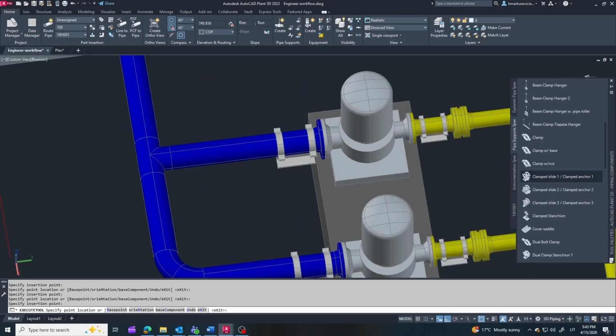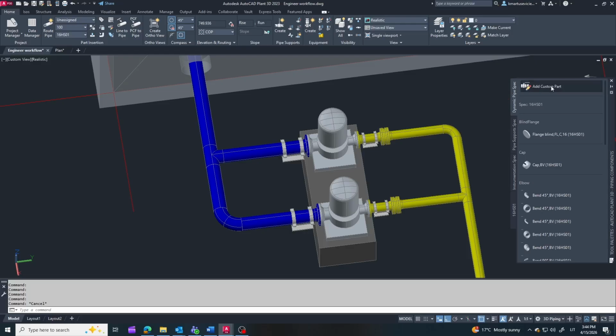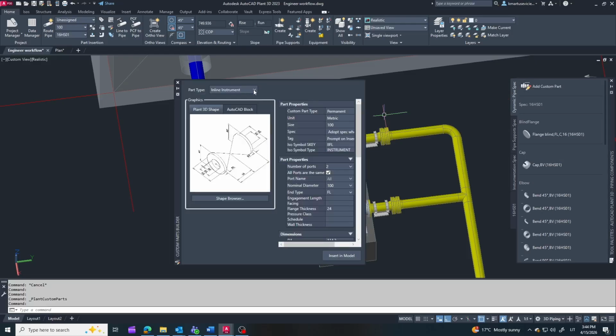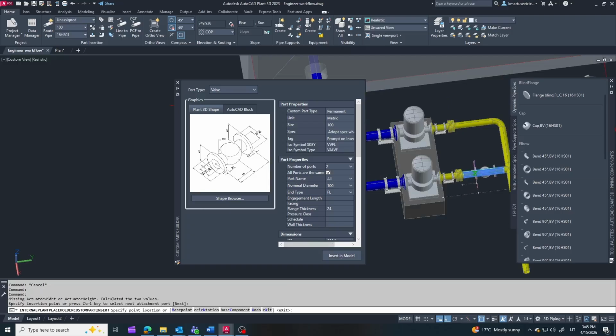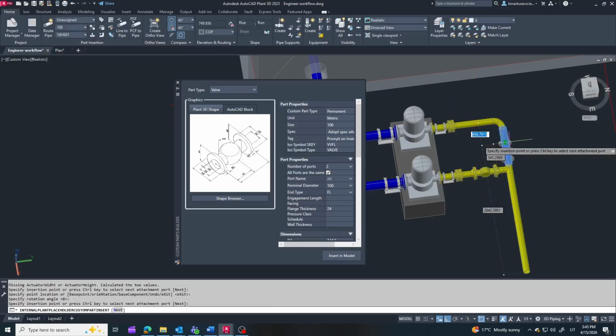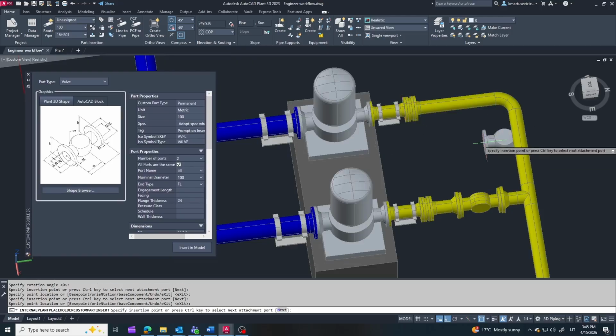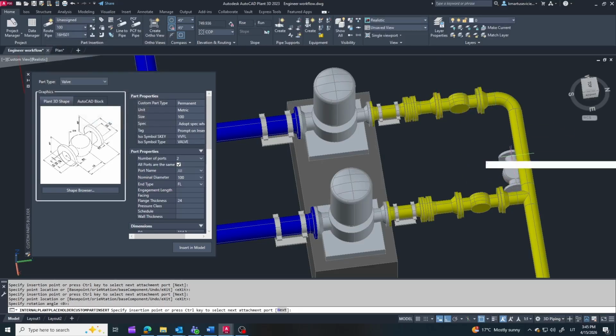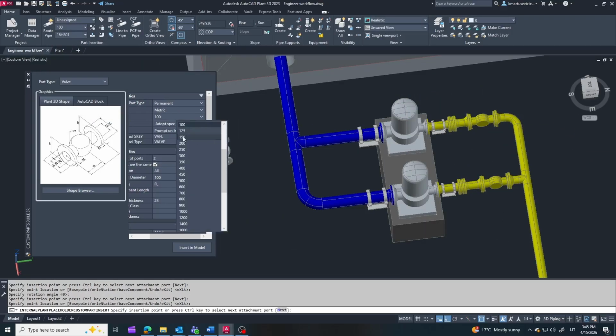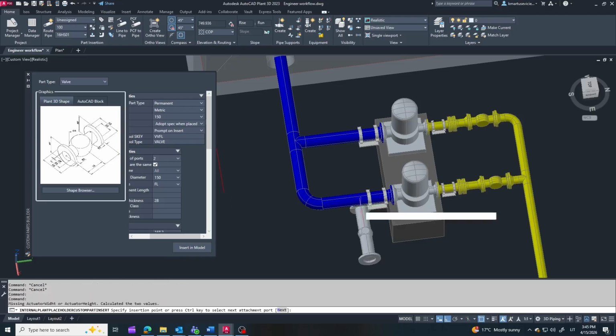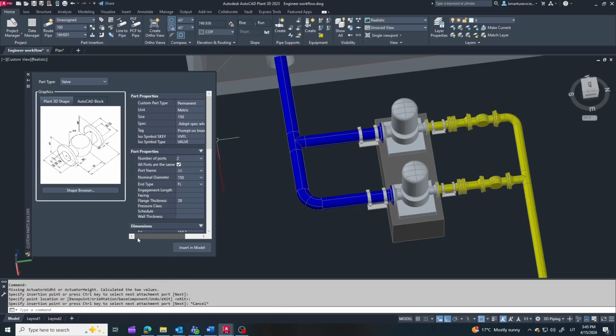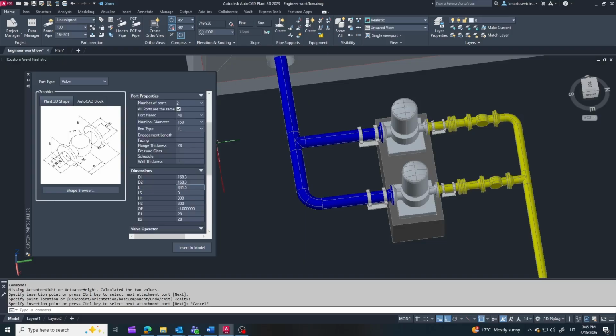Align supports in one line or in a single row. It saves space, reduces cost, and makes the layout look clean and professional. Remember, no equipment likes when loads are transferred to its nozzles. This is especially important when a valve, like a butterfly valve, is installed directly on the nozzle. In that case, always add a pipe support right after the valve.